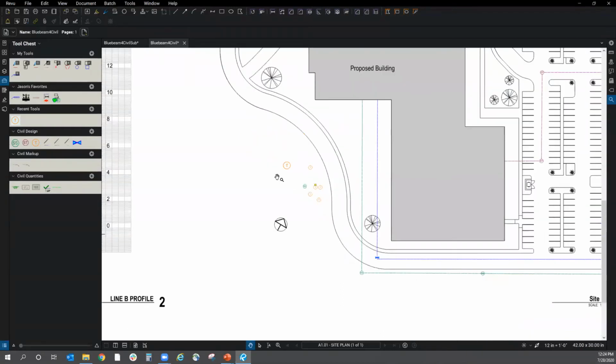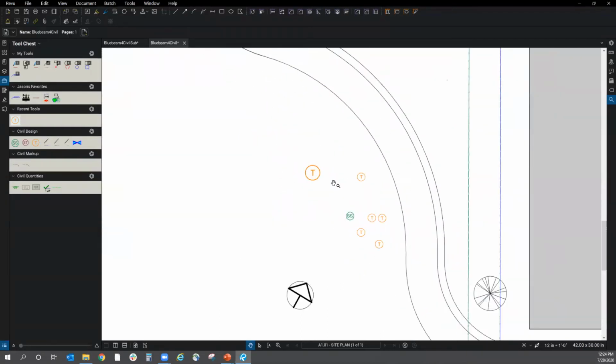Now the question is, is there a reason to use snapshots in lieu of creating a group? It depends on where you're getting this data from. Inside of Review, since I made these symbols in Review, I could easily turn those into a group. And if I had a good PDF, I could pull things and make a group from that as well. Using the snapshot allows you to use any PDF, right? So if you have a raster-based PDF, the same thing would work, where a group would not.